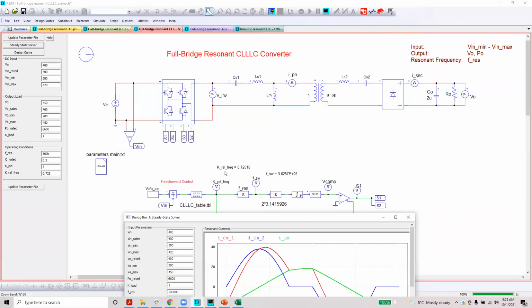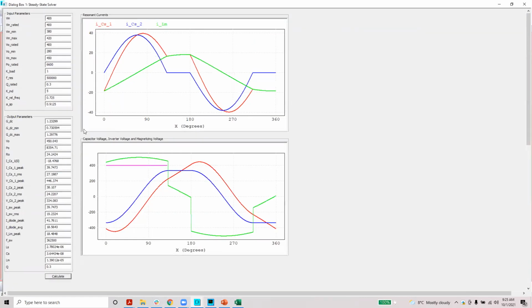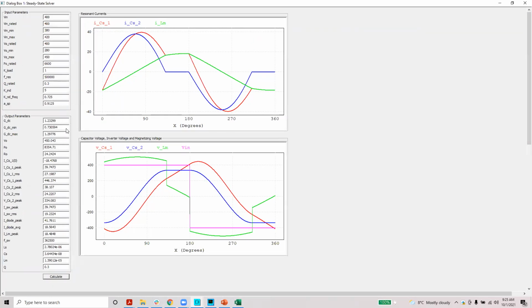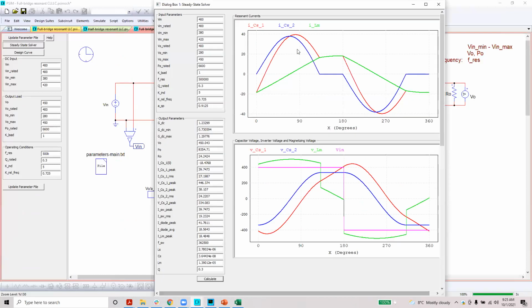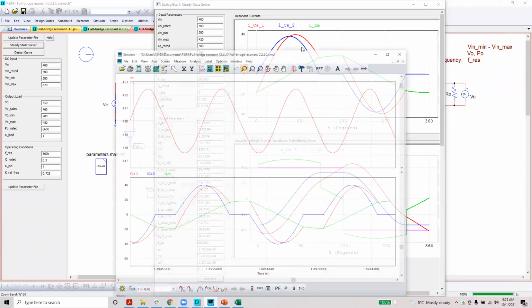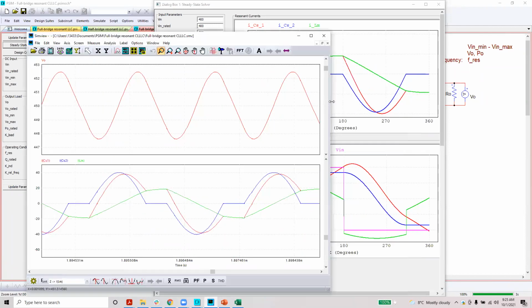So you always need to check how much in closed loop you got this frequency. So 0.725 to match perfectly. It's 0.725, right? So yeah, okay, fine. So 450 is the voltage here, right? 450 we have. And actually, this has a problem with the sizing, right? Anyway, so this voltage, this is for resonant CLLLC, you see.